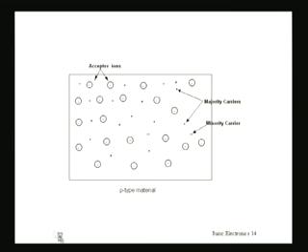So that means in a p-type material, the atom of the impurity will be an acceptor ion having a negative charge, and there will be holes which are positively charged as majority carriers, and also, although very less in numbers, there will be presence of minority carriers which are electrons coming from the intrinsic semiconductor.